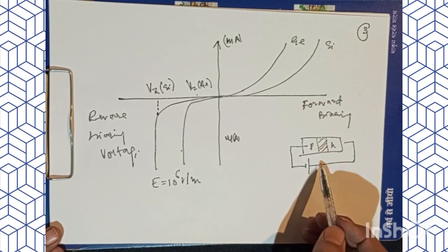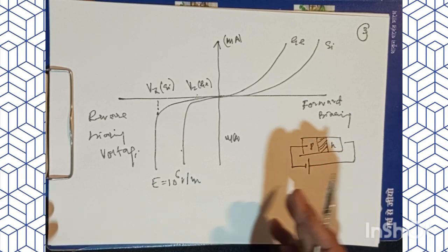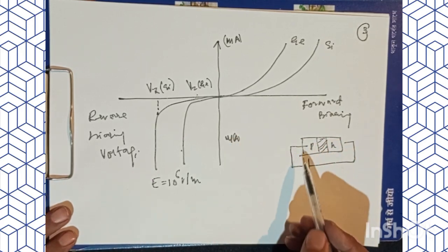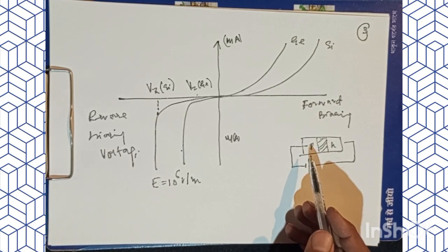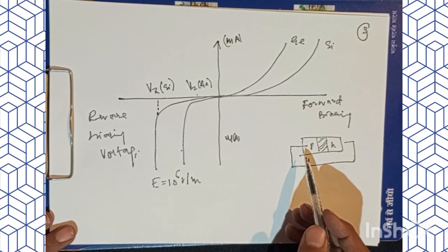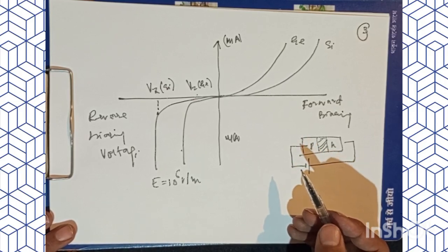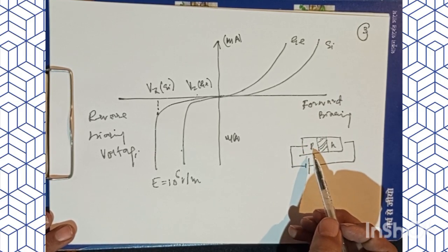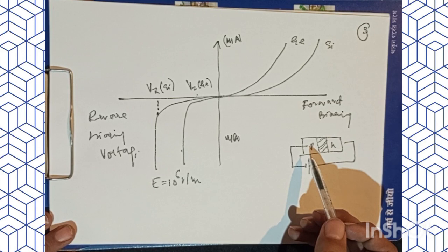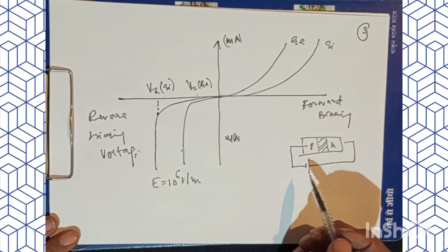This electric field pulls the electrons from the covalent bonds, which are accelerated from the P region to the N region. The flow of these electrons emitted by the electric field, which I told you in the beginning is called the ionizing electric field because it ionizes by breaking the bonds, across the junction is responsible for this large reverse current at the zener voltage.